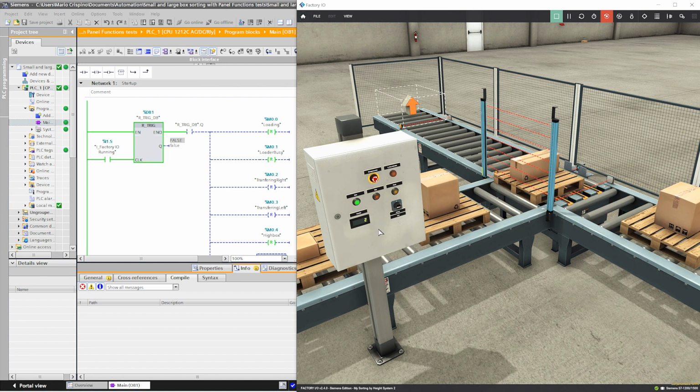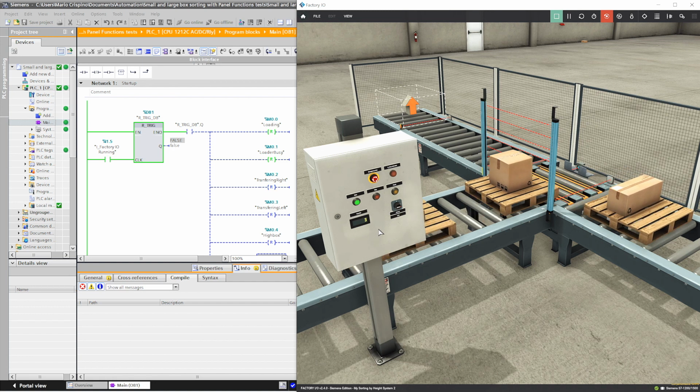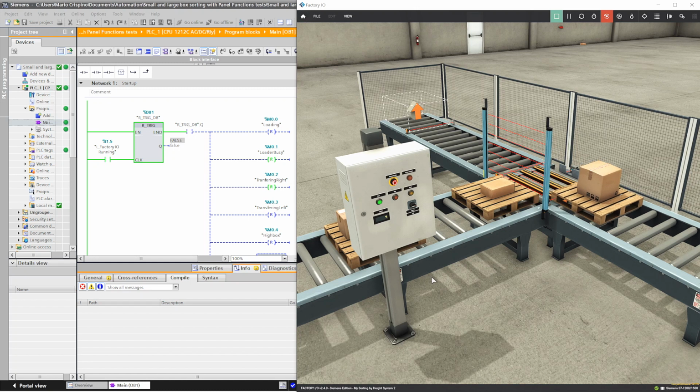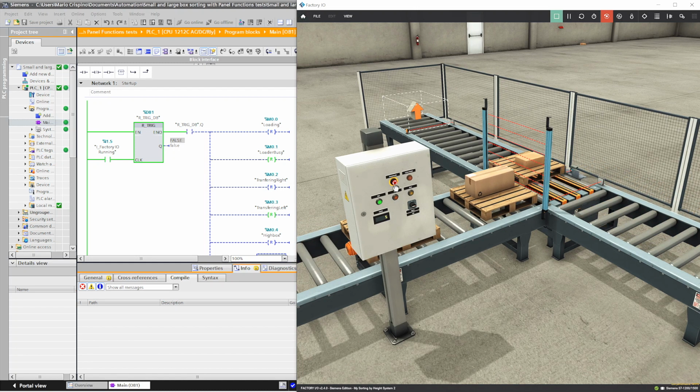Okay, this time we are going to select the emergency stop button to see what effect that has on the system. I'm just waiting to get a few small height boxes onto the left conveyor. Here one comes. As soon as it starts transferring, we'll press the emergency stop. The difference with the emergency stop is that for safety reasons, all the conveyors stop and the yellow bed and chains also disengage. Also notice that the e-stop activated light starts flashing, which helps distinguish from a general stop.